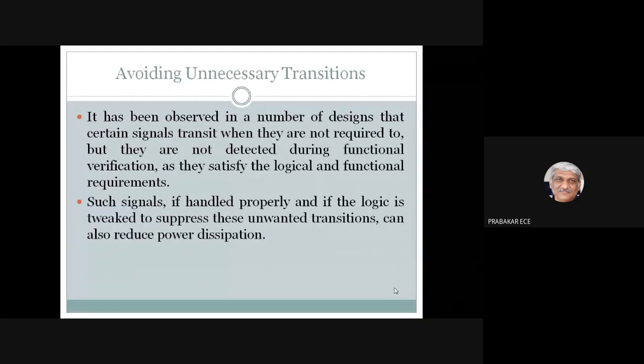So instead of going for latches, if you go for registers, which are edge triggered devices, during the edge the value will be either 0 or 1. So in that case, only one value will be passed. I think you can visualize what I am saying, right? If it is a normal class, I can explain all these things, but with the PPT I am unable to do a simple demonstration. But I think you can understand, right?